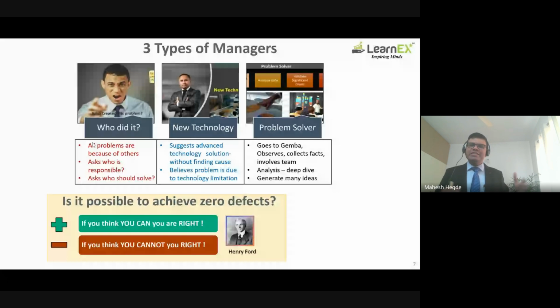They have listed some 100+ parameters which can influence the mileage, in other words, the fuel consumption of the engine. Then I suggested that you take engines and test them in test bed 1, test bed 2, test bed 3. They have 7 test beds. They tested the same engines in multiple test beds. Results were different. It is measurement system analysis.